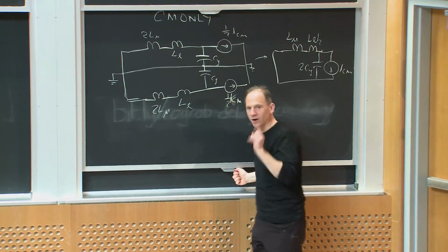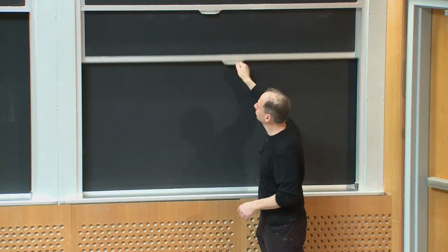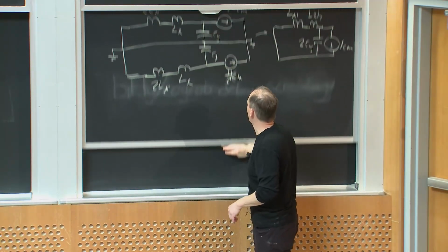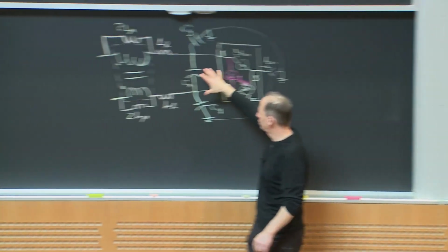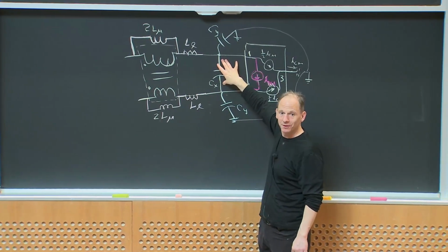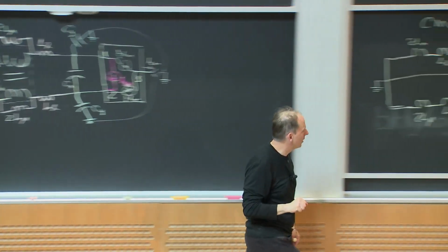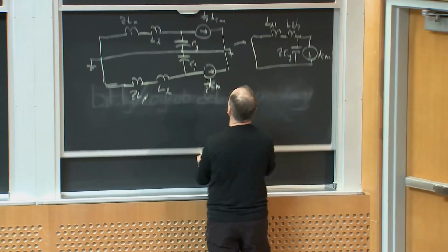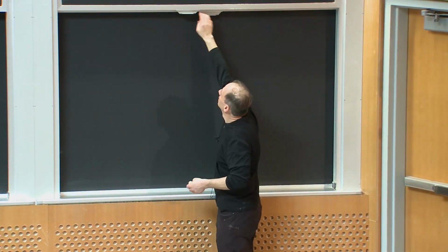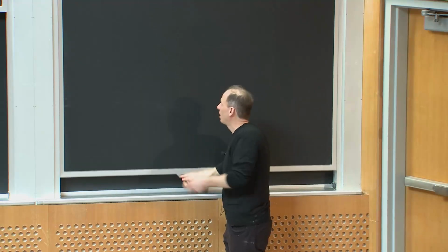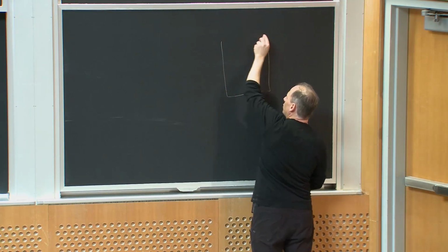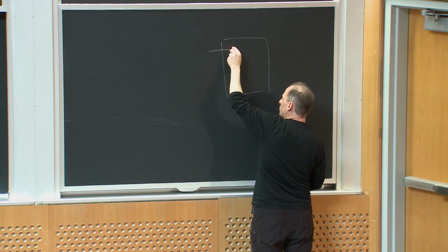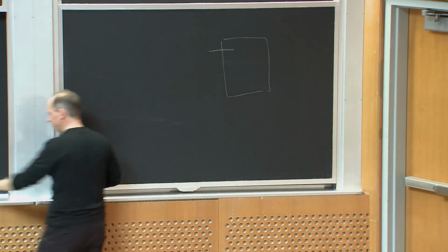Let's think about differential mode only for a moment. And you notice when I drew the common mode filter, I completely ignored this X capacitor because it's not doing anything for the common mode component. Let's think about the differential mode only. So suppose, here's my device, right? If I'm only thinking about the differential mode components, I have IDM.